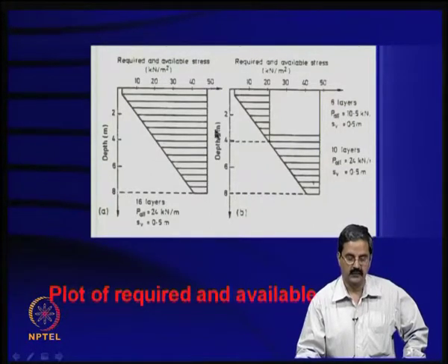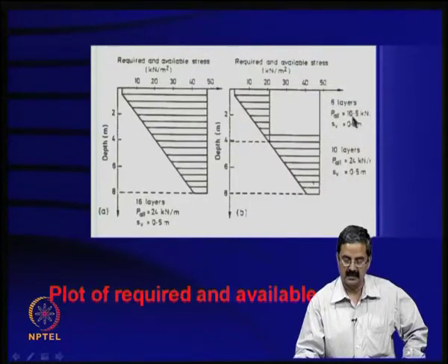If you use a very good material with 24 kilonewtons, it is not worth having 16 layers; it is underutilized. So, one way is that you take the 10.5 kilonewton one and then have spacing, and you can put up to some layers wherever it comes in.